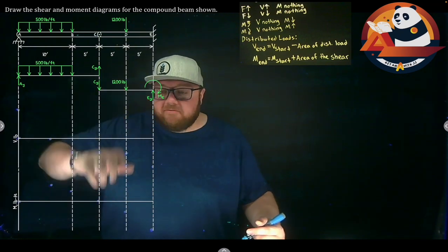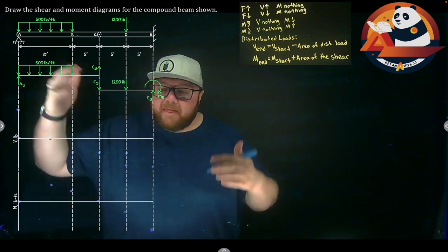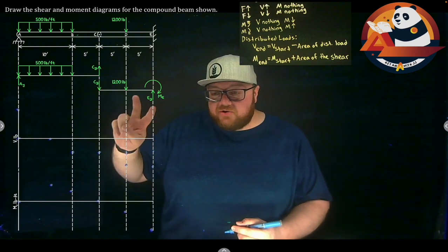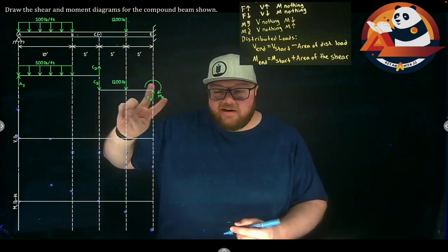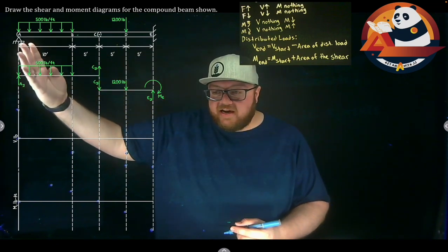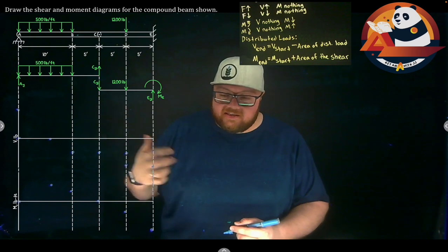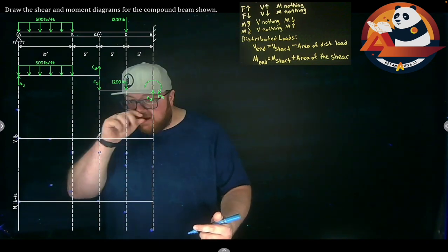If I'm trying to make a shear moment diagram, I need these support reactions. So we explode this and we treat it like a frame so I can find my support reactions. So let's come and look at that. Again, I can do two equations per thing in here because I have already used my X equation to say AX equals EX, or AX equals CX and CX equals EX. Same idea in there. We have forces in the Y and moments. They're really all I can work with in here.